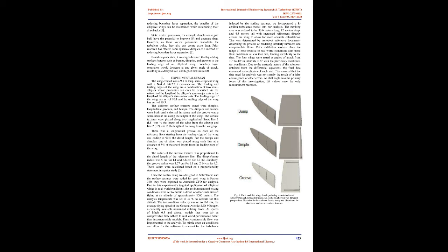By implementing technologies that could maintain the attachment of this boundary layer to the wing, the stall angle could be delayed. Additionally, because the coefficient of lift increases with angle of attack, if the boundary layer could be maintained at increasingly higher angles of attack, the airfoil would be able to reach higher coefficients of lift, creating a more efficient system.